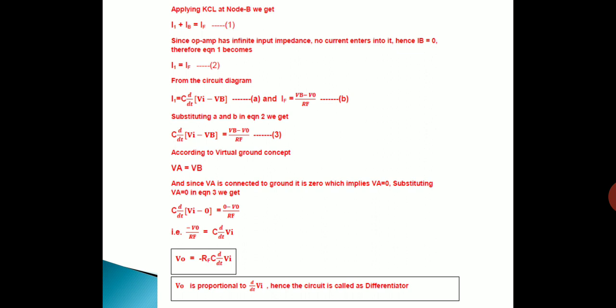Since the op amp has infinite input impedance, no current can enter into the op amp. Hence, the current IB should be 0. So, if you substitute IB equal to 0 in equation 1, we get I1 equal to IF. We can call this equation 2.